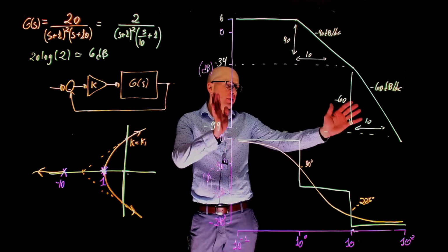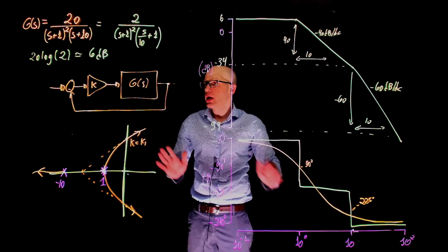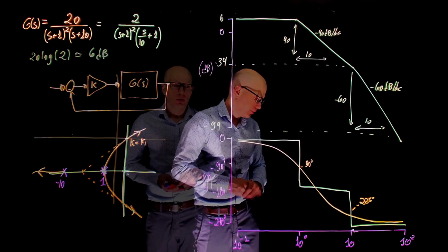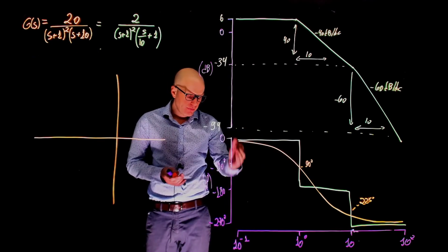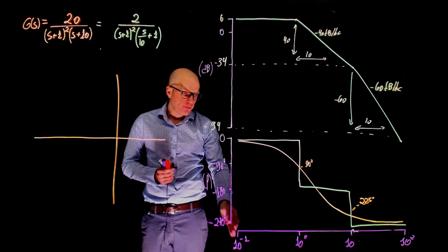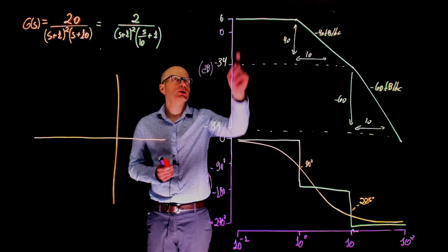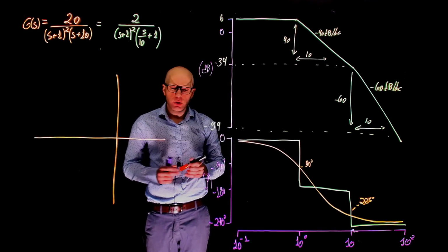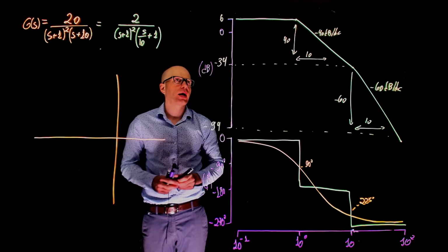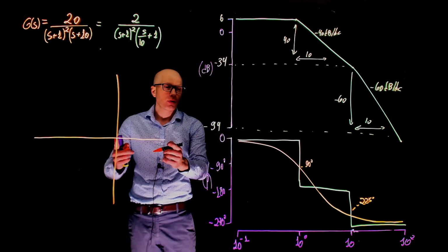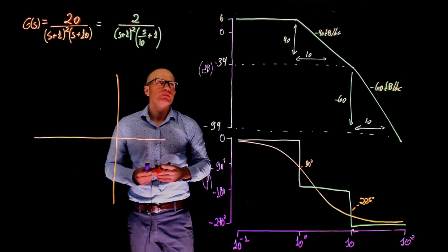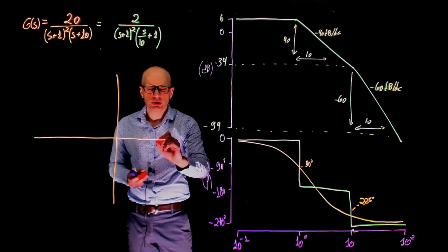Now let's take advantage of the Bode plot that we have here and come up with the Nyquist plot first. Now let's go from the Bode plot to the Nyquist plot. At very low frequencies, the phase is 0 and the magnitude is 6 dB. So we are sitting on the positive real axis. Remember that this is now in regular scale, so this is actually the inverse.